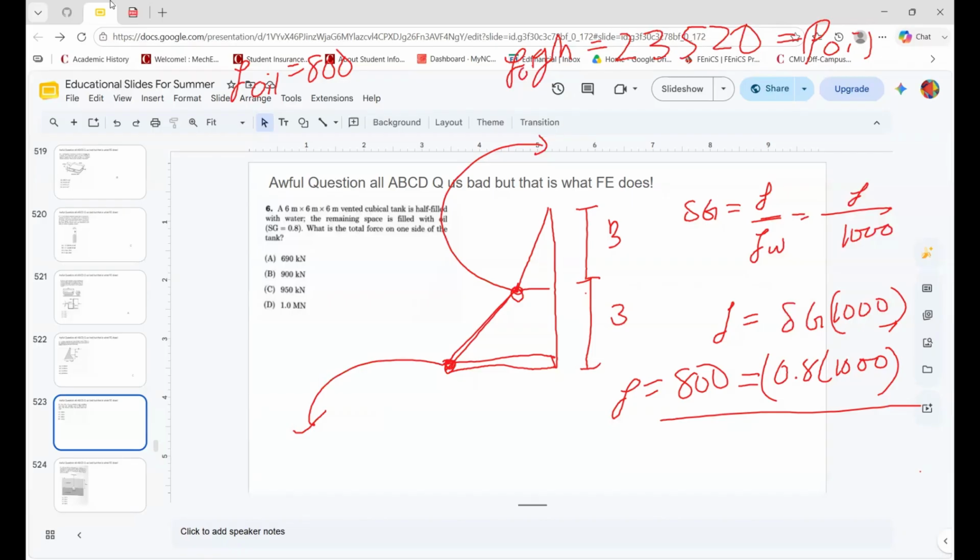So this one is going to be P, and it's going to be equal to P1, which is oil, plus rho water g h. So you'll see over here that you grab from the previous and do plus 1,000 multiplied by 9.8 multiplied by the height, which is another 3. We have equivalent to that 52920 newtons, basically. With that said, we have this.